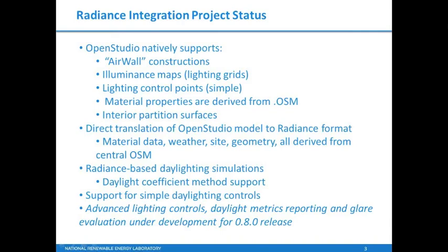So right now we're just evaluating illuminance at the work plane, and when that set point is met through daylight alone, the lighting power fraction is at 0. When it's not met at all, the lighting power fraction is at 1, and if it's somewhere in between, it's somewhere in between. So it's a pretty crude lighting simulation or daylighting control simulation, but it's really no different from what tools like DaySim do today.